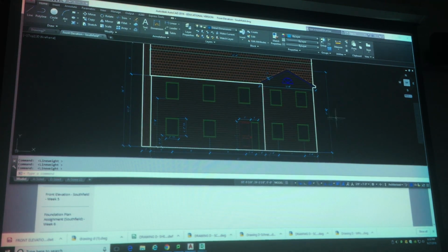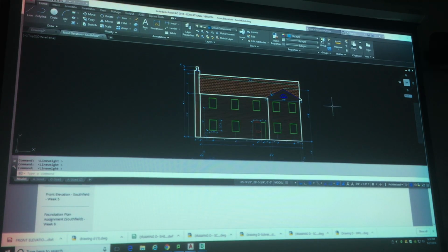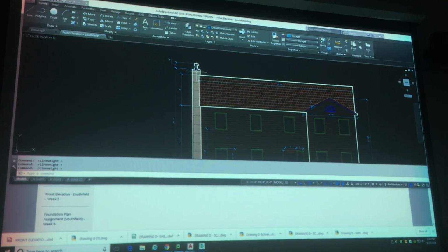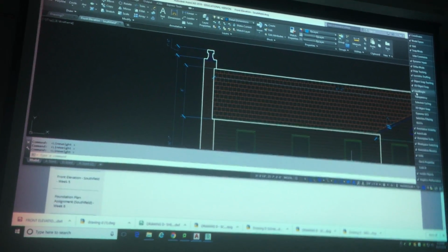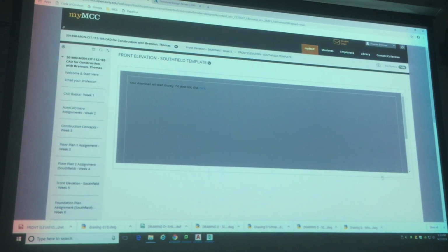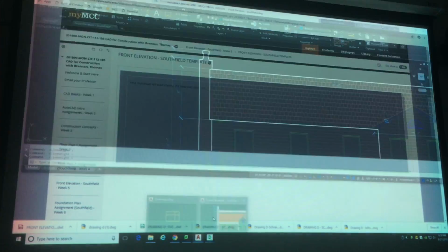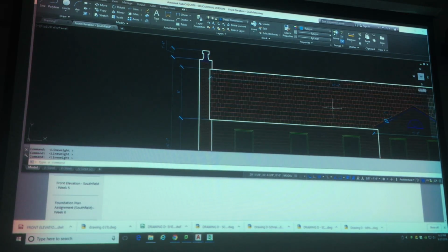There is a profile that I used right here to draw this, because once again, it's an elevation, so that's the line that I used for that. So we can see that it does have a thickness. If you don't see the thickness, you need to make sure that the line weight has been selected, there's a check in it, and then you also have it on over here. So we've got that.